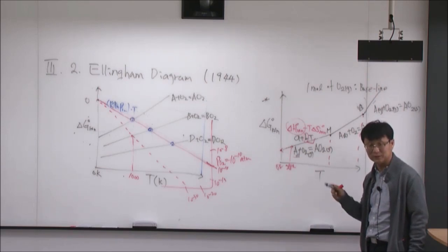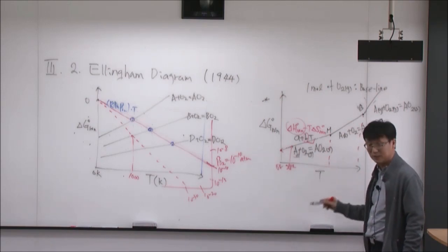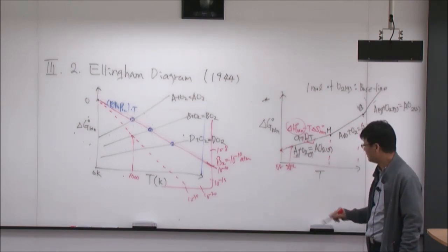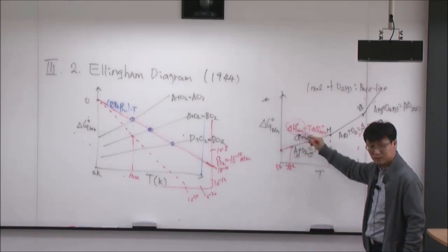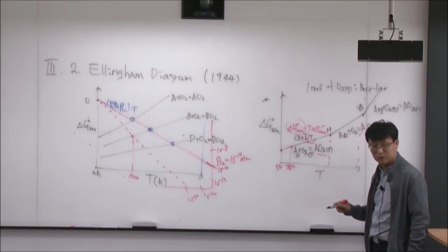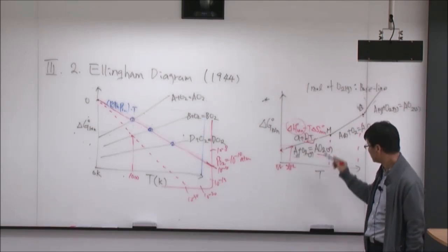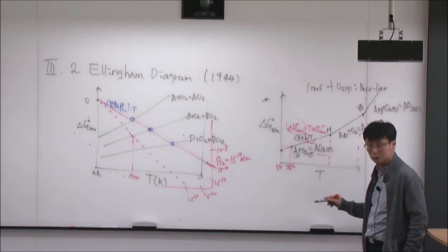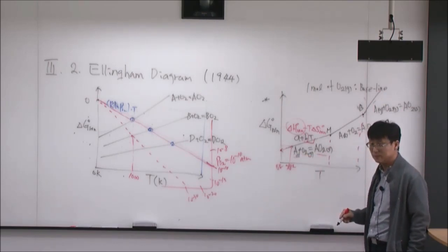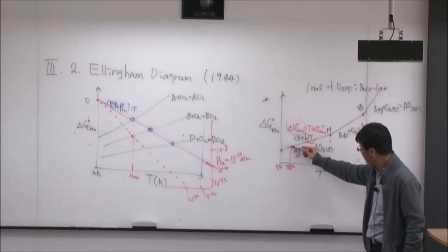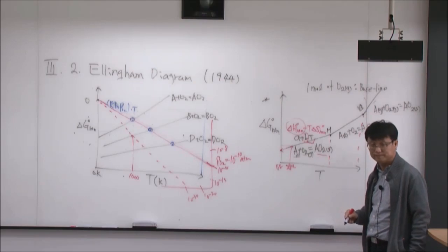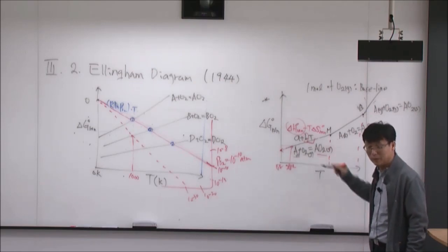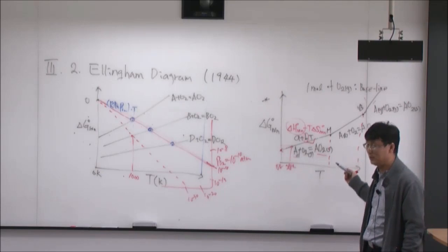That's a typical reference state for A solid. Oxygen's reference state at 298 Kelvin is O2 gas phase. So when you know the delta H of reaction, that should correspond to the standard enthalpy of formation for AO2 at 298 Kelvin. Because you know the slope, from delta G you can calculate the delta H at 298 Kelvin. There's a lot of thermodynamic information involved inside this one graph.